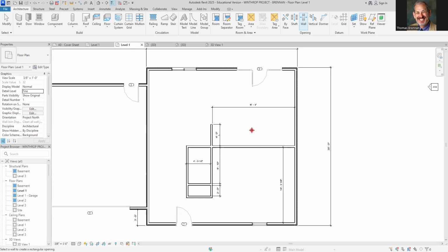So I clicked on the wall. So click on that wall. And okay, now it says enter starting point. Now again, down here, enter starting point of rectangular opening. So let's go ahead and pick a point here. And let's go ahead and go here to, and it's supposed to be 12'4". I'll just go ahead and get it close. I'll just drop it there. And okay, so I've got it there.